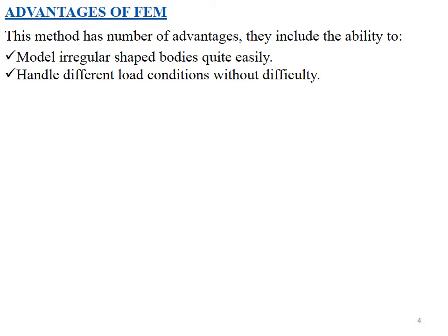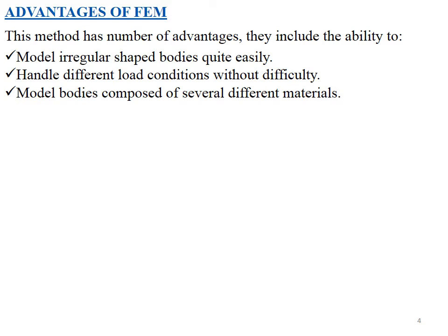When there are many loading conditions in a problem, like loading at different places, different types of loading, and different boundary conditions, at this point of time, this FEM method is quite useful in comparison with other problem solving techniques. Model bodies composed of several different materials. Nowadays many composite materials are used in many of the industries or sectors. These composite materials also can be modeled by this FEM method, which may be difficult to do in other problem solving approaches. So this FEM method makes the modeling of bodies composed of several materials easier in comparison with other techniques.